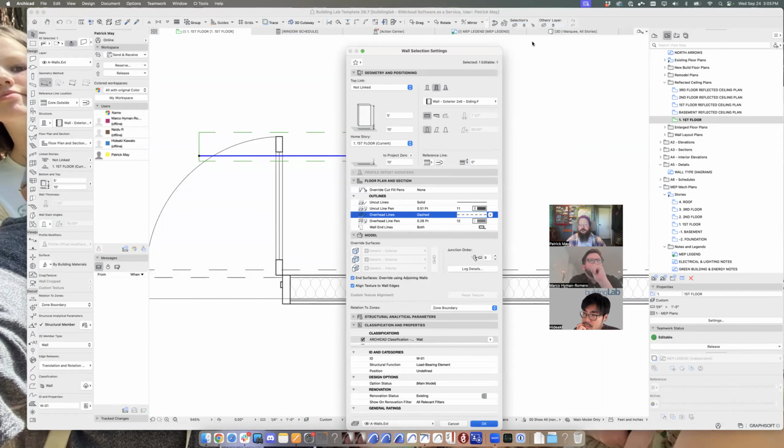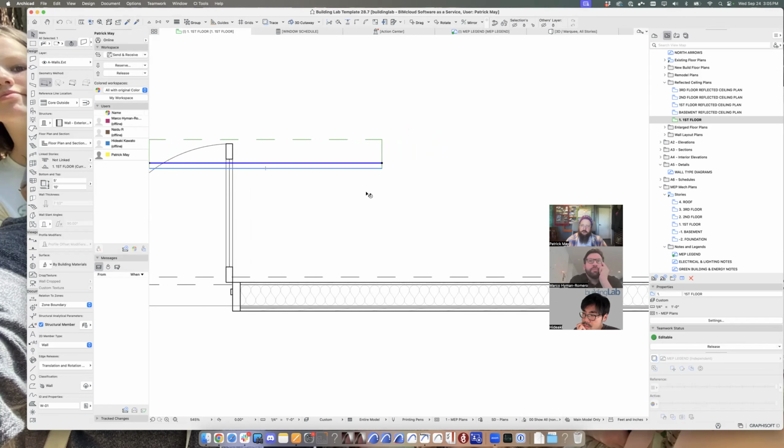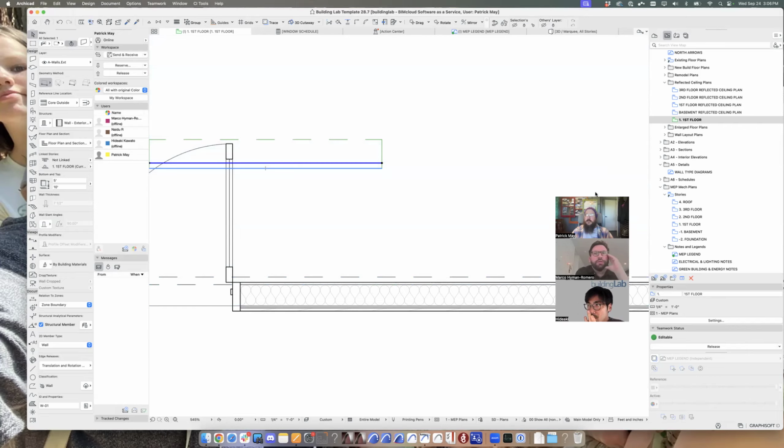Okay, cool. So like you mentioned, a mezzanine being a really good example of all of these options. Would a split level house also be kind of the same thing, or would you recommend different stories for that? So my general rule on stories for split levels: if the split levels are more than 42 inches apart, I usually show them on separate stories.